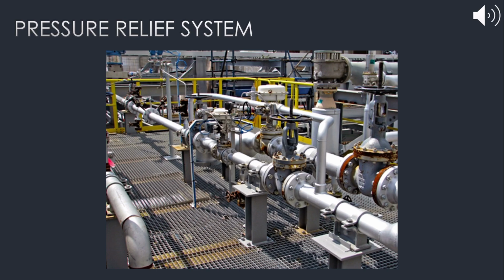A relief system is an emergency system for discharging gas during abnormal conditions by manual or controlled means or by automatic pressure relief valves from a pressurized vessel or piping system to the atmosphere to relieve pressures in excess of the maximum allowable working pressure.